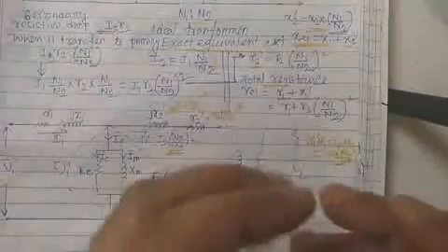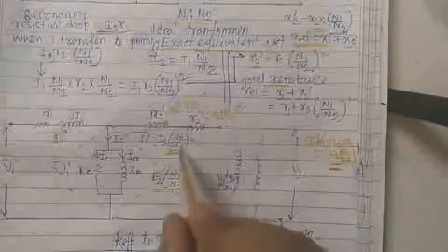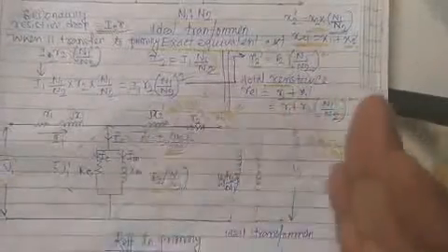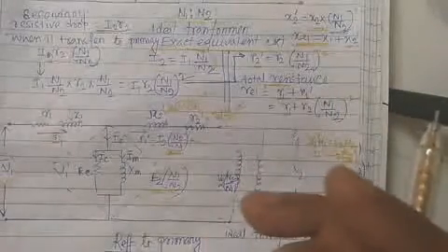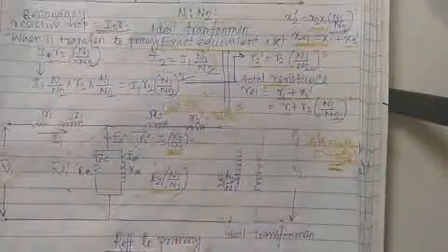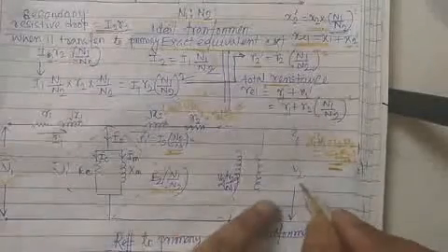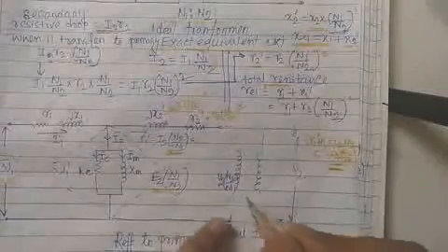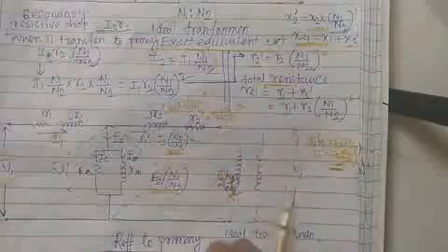Now as we know, the I1 dash, that is the compensating current, is equal to I2 into N2 by N1, from this equation. When we are transforming the current, the multiplying ratio is just the opposite. Remember that. Similarly, when the induced EMF E2 is transferred to the primary, it is multiplied by N1 by N2. When the terminal voltage V2 is transferred to the primary, V2 is multiplied by N1 by N2. Very simple. So this picture shows the single phase equivalent circuit referred to the primary.